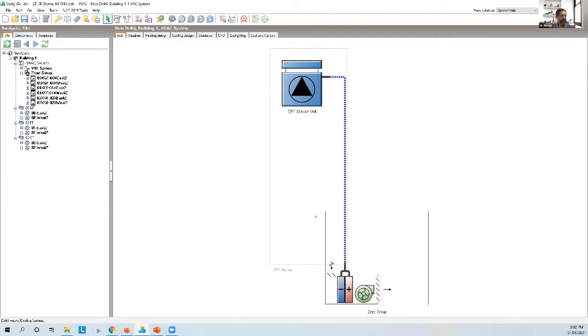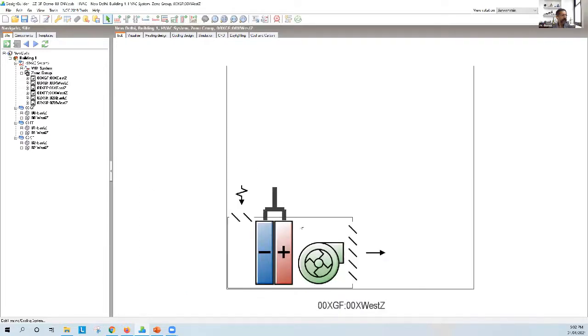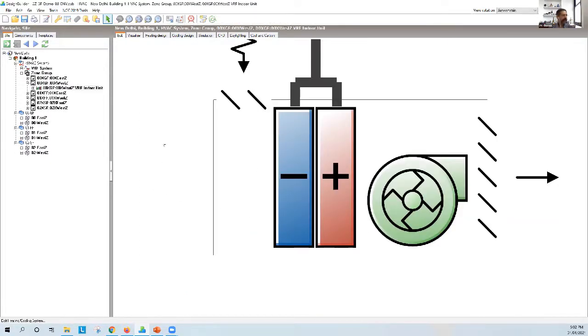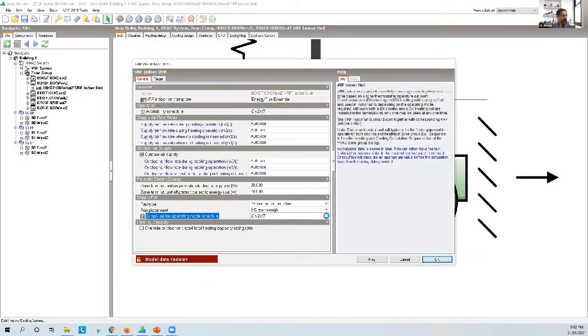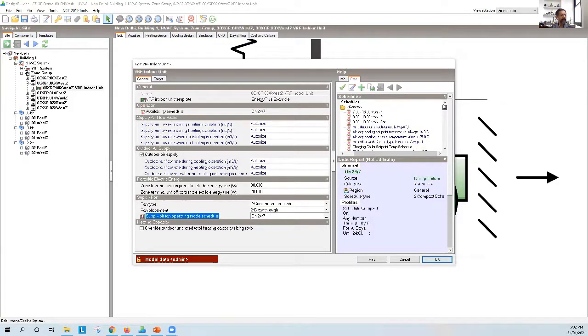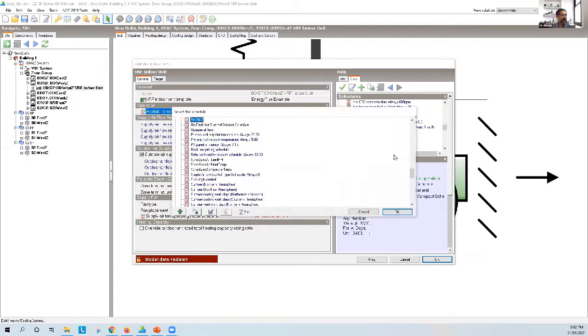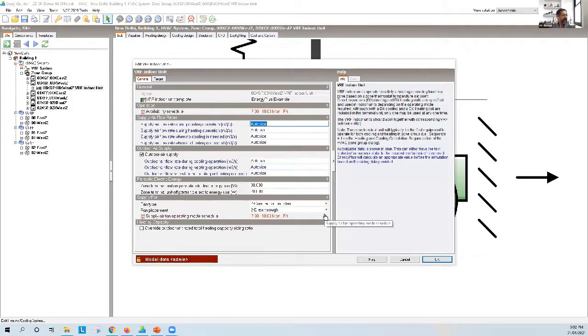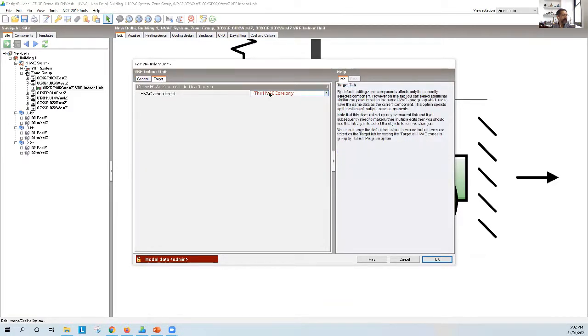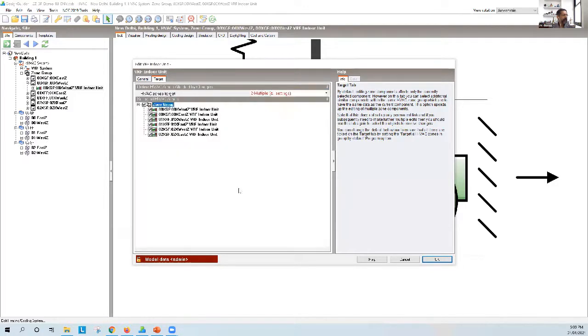And again, the one other thing that you may want to do before you run is to make sure you have included the outside air component for this as well. So if you right click at this level, you can switch on the outside air supply as before, and change the schedule for when the system runs to something that's correct. So I'm changing all of these two schedules to the 7 to 18 Monday type system, and then make sure you apply that to all the systems that you want to do that for.